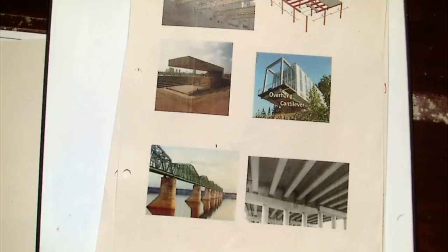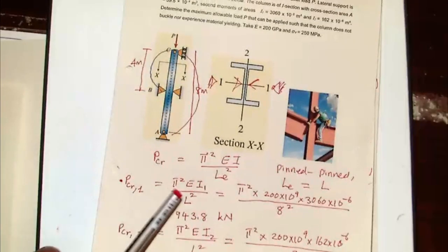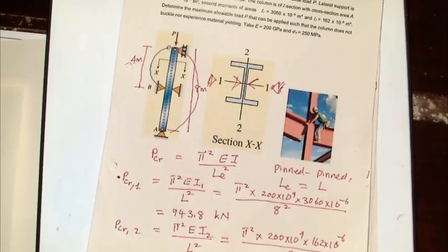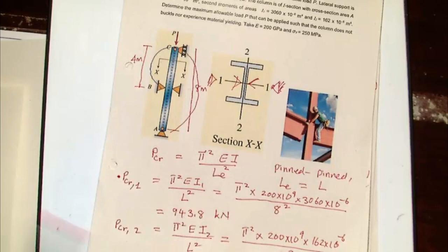So if you calculate the load required to support a particular weight, and you think that the column you have is likely to fail, either by yielding or buckling, then the question you might ask yourself is: I need to support this weight. Is there any other way I can do that? One, you can go back and change the material, which gives a different modulus. You can make the cross-section bigger, so you increase I, or you can make the length shorter. But if none of those is actually possible, then you can add additional structure.